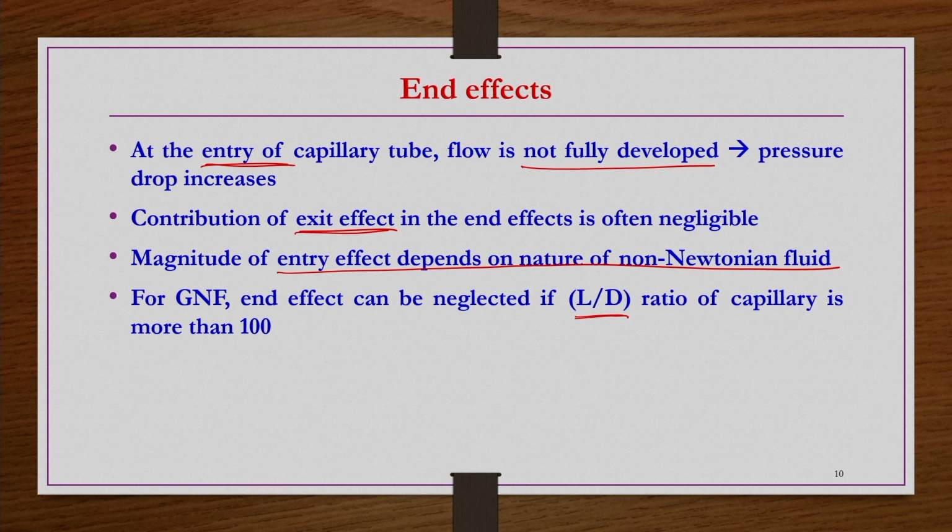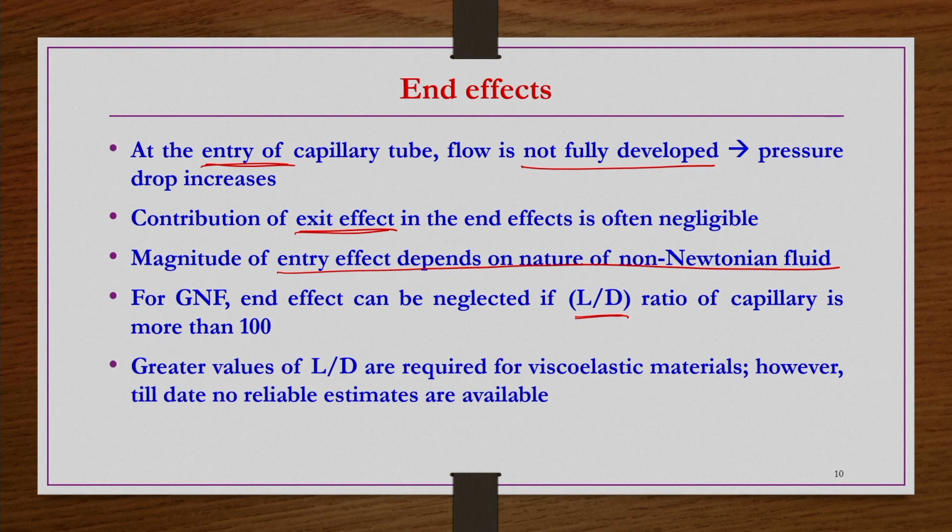If you are maintaining L by D more than 100 or 150. But for other fluids like viscoelastic materials, even 200 may not be sufficient, and there is no concrete data available on how much L by D value is sufficient for viscoelastic fluids; that is not known yet. But it has been observed that even L by D of 200 or more may not be sufficient to avoid end effects in the case of viscoelastic materials flowing through capillaries.